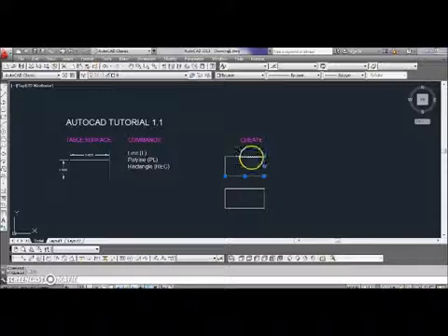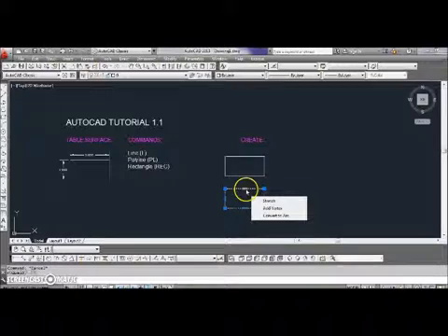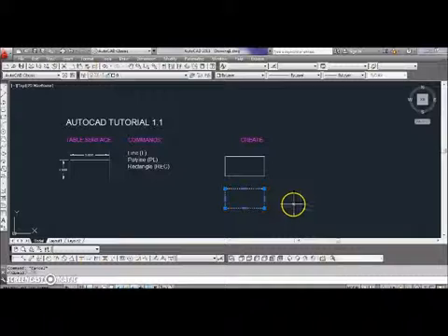If I click on the first drawing, I can pick my lines separately. They are separated. In the second drawing, where we used a polyline, all the elements are one shape. All the lines are joined. So we have our first two commands used, and now we're going to jump to the third command that is called rectangle.